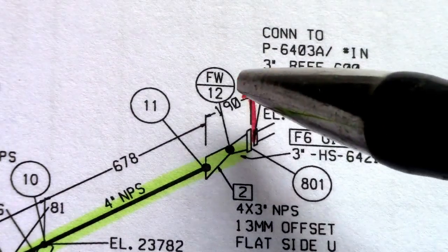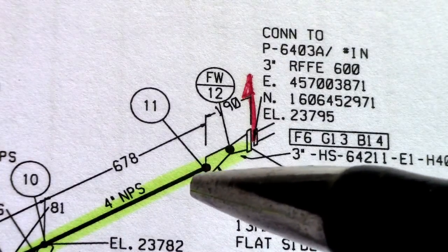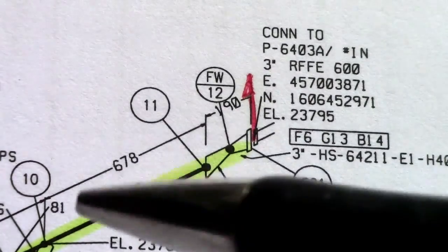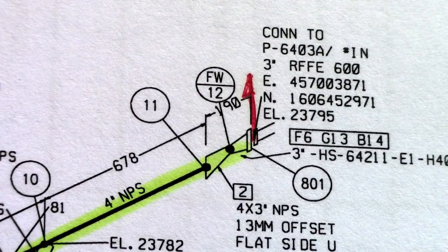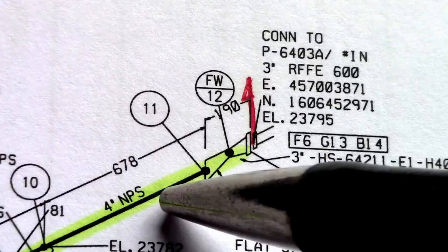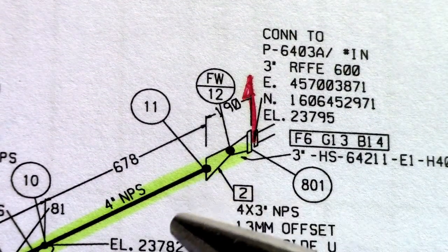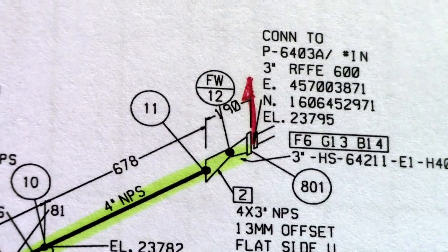Check the joint if this is already fully welded. Sometimes they have put a tape around it. You must check that. Remove the tape. Sometimes they have not yet fully welded, only tacking. Check the specification, all the material installed here based on the isometric. Check all the specification, what type of materials.